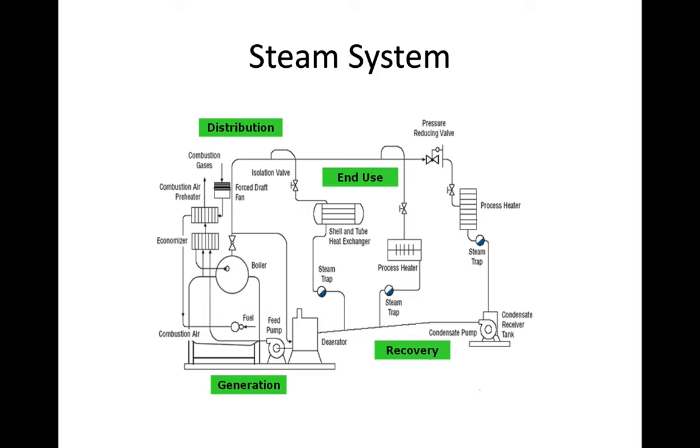This treatment, including chemical treatment. So we need to inject the chemical substance into this water treatment. But if we can recover 100% of the steam from the user to the boiler, we don't need to treat this water, because it is already suitable for the boiler purpose.